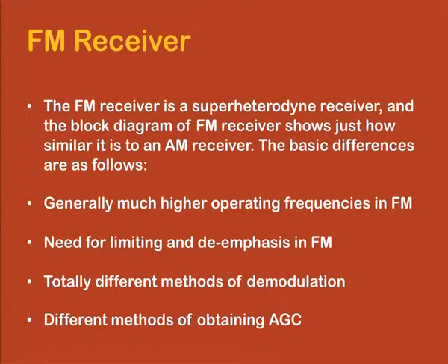If viewers can recall, we have talked about pre-emphasis and de-emphasis circuits in connection with the effect of interference on FM signals. We can recall that the effect of interference in FM signal is linearly increasing with frequencies, whereas the effect of interference on phase modulated signals is constant.